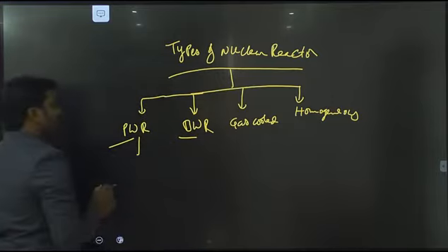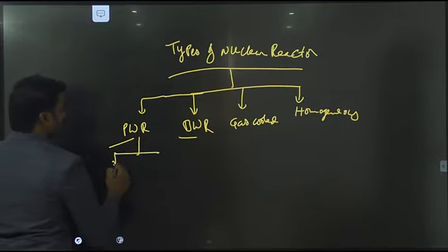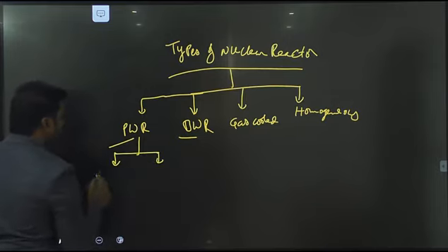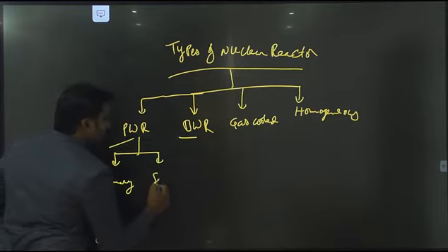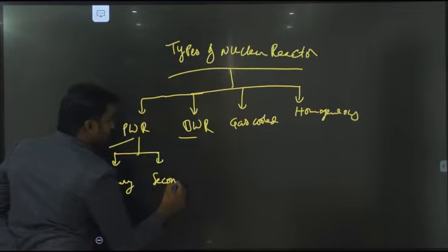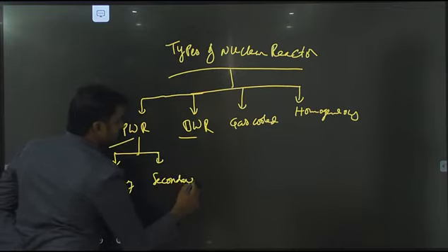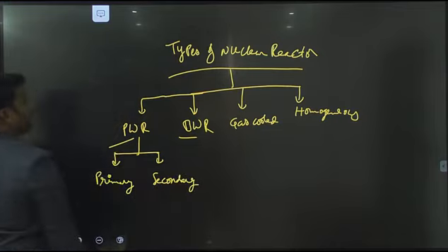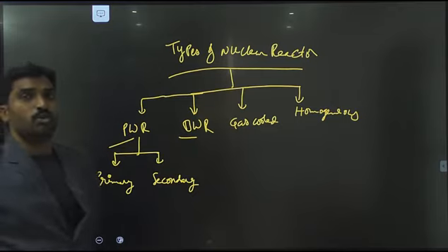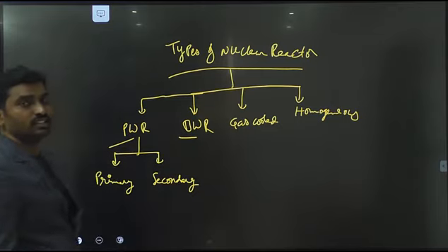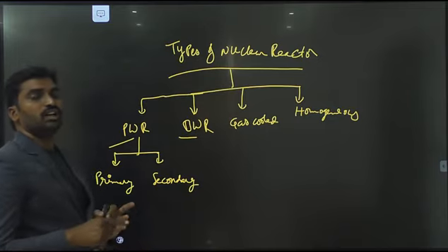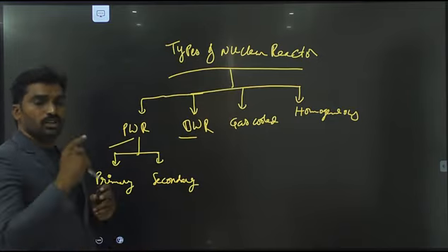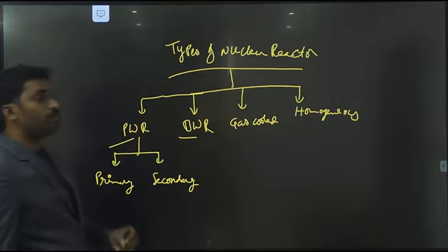In a pressurized water reactor we mainly have two circuits, the primary circuit and the secondary circuit. So what is the process of a PWR? We send the water through two circuits. In the first circuit, the water is brought to high pressure by using a pressurizer.